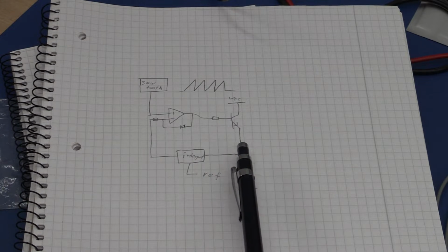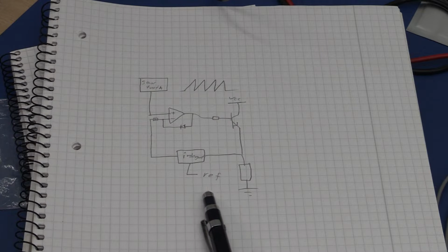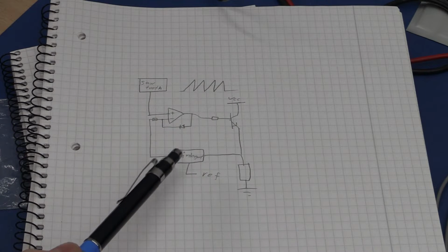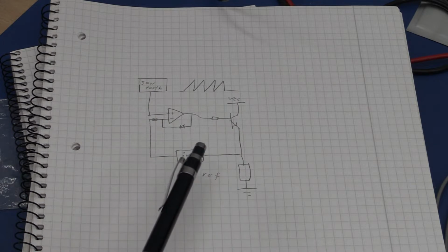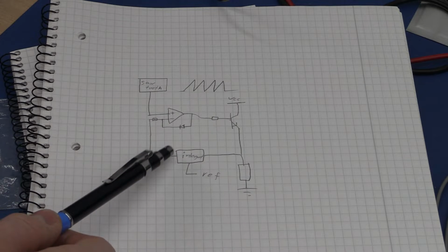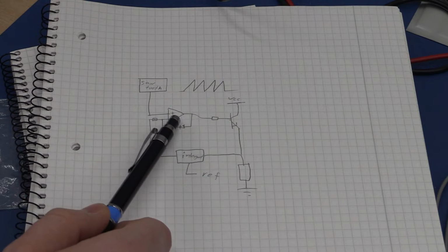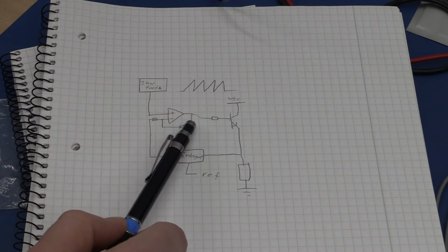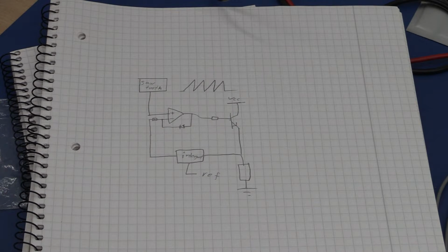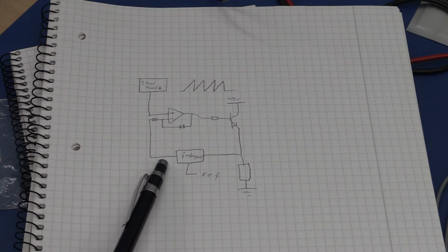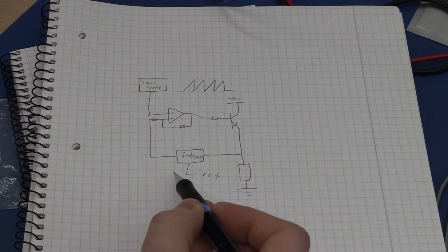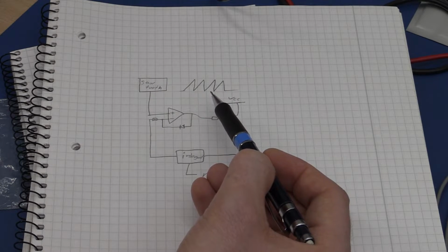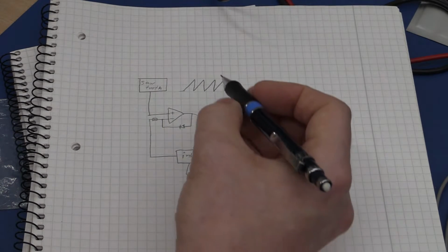So as long as the voltage here is lower, the output will continue to decrease over time. Once it is at the correct voltage, it will stay stable, and once it starts to decrease, the output will go up. I think this would be the ideal solution, but if we cannot get it stable, maybe we can do something else, but I think I will give it a try. We feed that into a comparator and we compare it to a sawtooth wave. And that is what generates the PWM signal for the transistor.